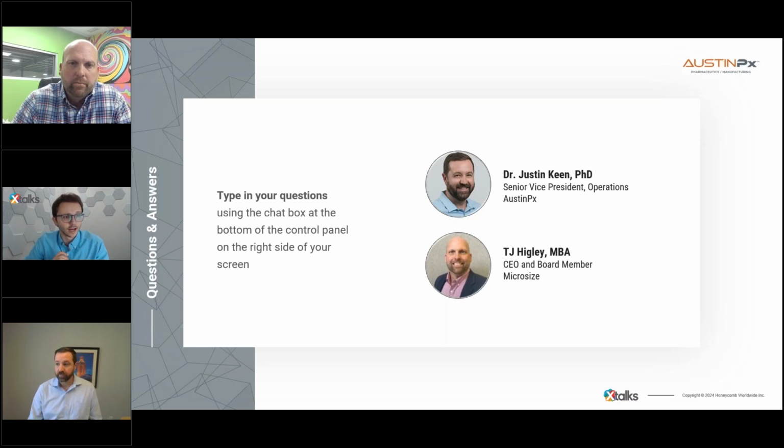Great, excellent. Thank you for that. Another question that's come in here from the audience. This audience member was asking about product contamination. So the question was, how do you lower that risk between two sites? I can help with that. So primarily that's just rigorous cleaning protocols. So the deep understanding of how to disassemble, reassemble, and break down that equipment. So every square inch is addressed and not only cleaned, but then visually inspected and then able to be swabbed for chemical residual. We test using HPLC for that cleaning verification.